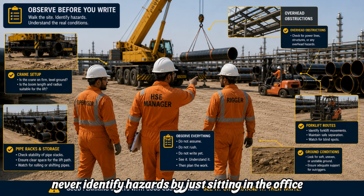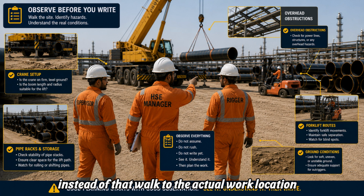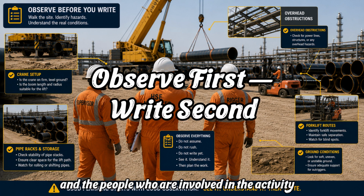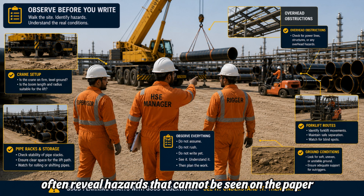Never identify hazards by just sitting in the office or copying a previous JSA. Instead of that, walk to the actual work location, observe the environment, observe the equipment, materials, nearby activities, and the people who are involved in the activity. The workplace often reveals hazards that cannot be seen on paper.